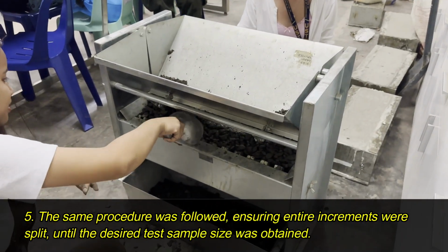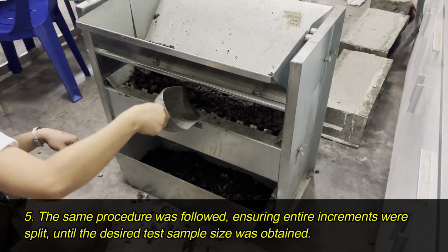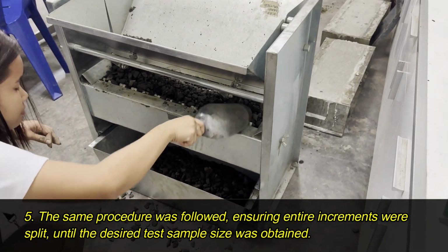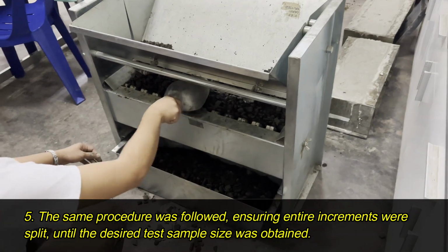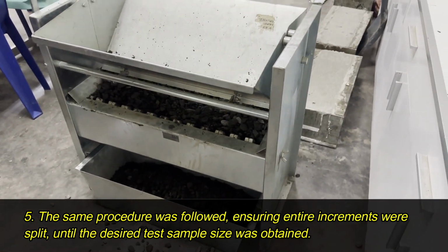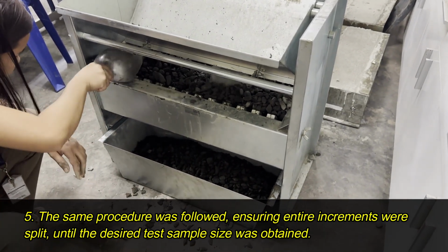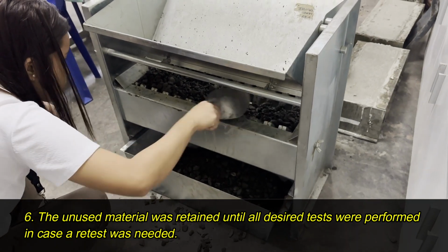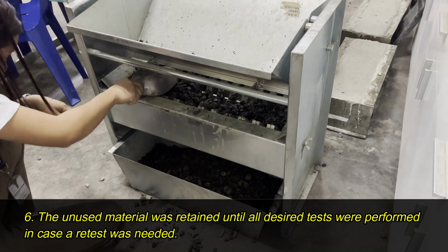Fifth, the same procedure was followed, ensuring the entire increments were split until the desired test sample size was obtained. And the last one, the in-use material was retained until all desired tests were performed in case a retest was needed.